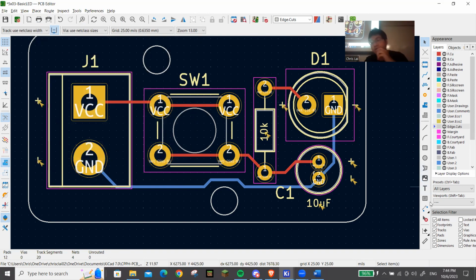You can also check, by the way, if you click on this ruler symbol down here, and you can check between one hole and another. Actually, the radius is 50 mils. The diameter is 100, which is good that I checked. So you can check using the measure tool. There's a ruler down there, and you can check that the holes are 100 mils in diameter. And again, this is about 0.1 inch or 0.01 inches.